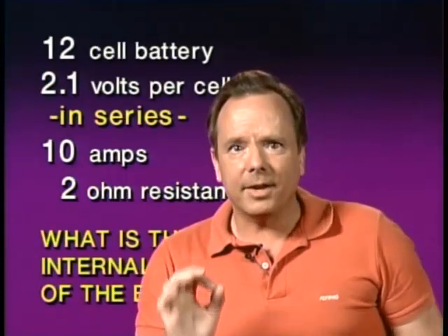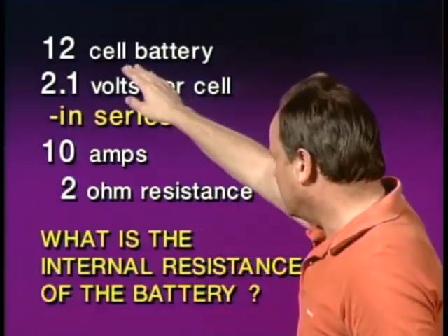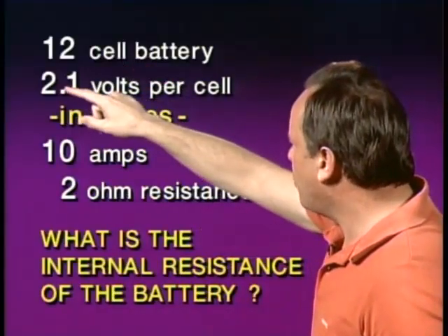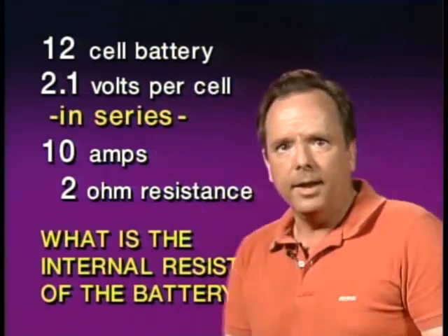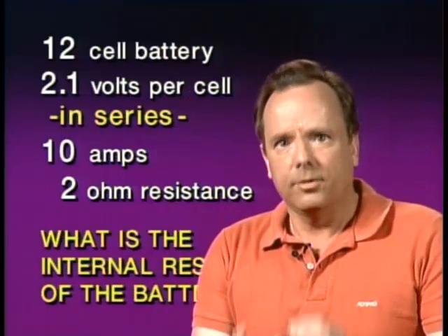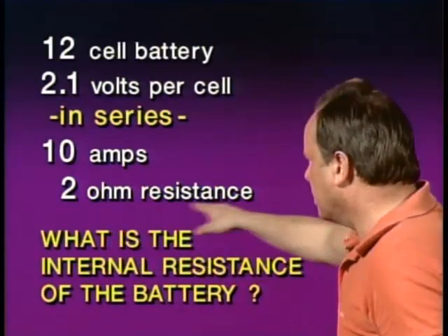Okay, here we are, Ohm's law. The current is equal to the electromotive force in volts divided by the resistance in ohms. The electromotive force in volts was 28. They told us that. We just figured out the total resistance for the circuit is 30 ohms. So the current for the entire circuit is 0.93 amps. And that's the answer to the question.